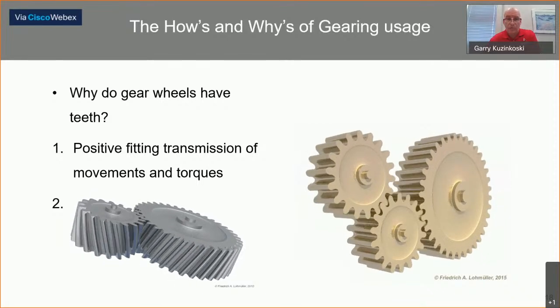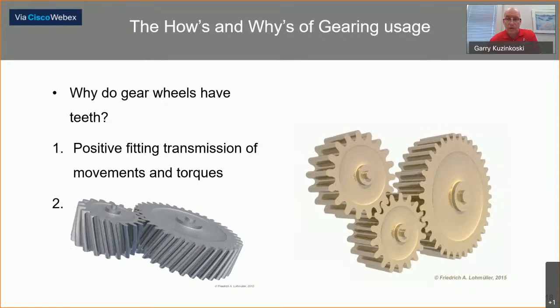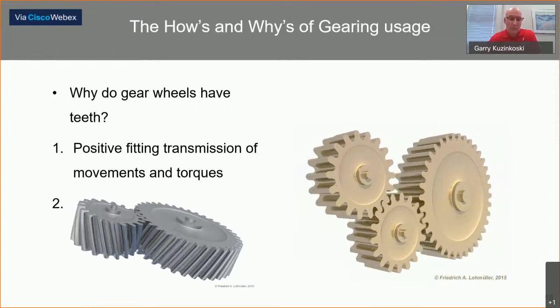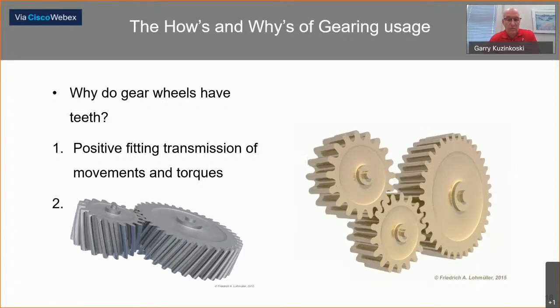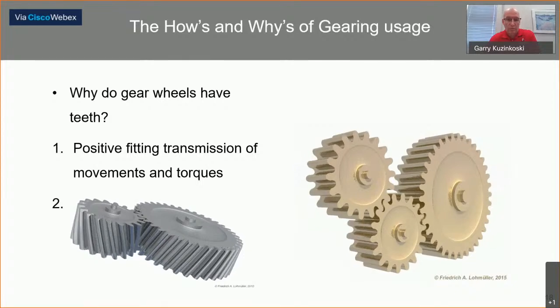There are people that use in automation actually wheels. So they might be something covered with a rubber or some other type of material, or they could be just a metal wheel by itself. What happens in that case, though, is you can have slippage. You're not going to get that with a gear tooth.